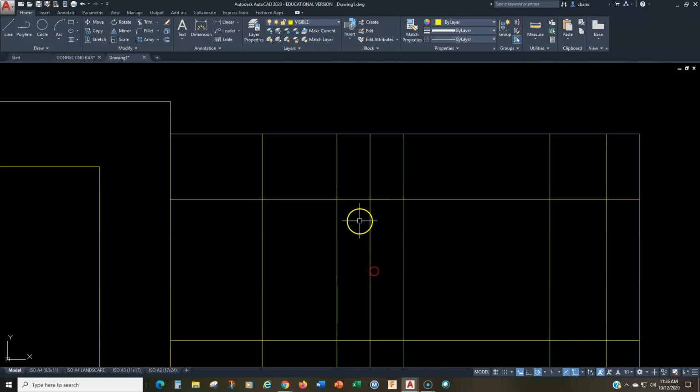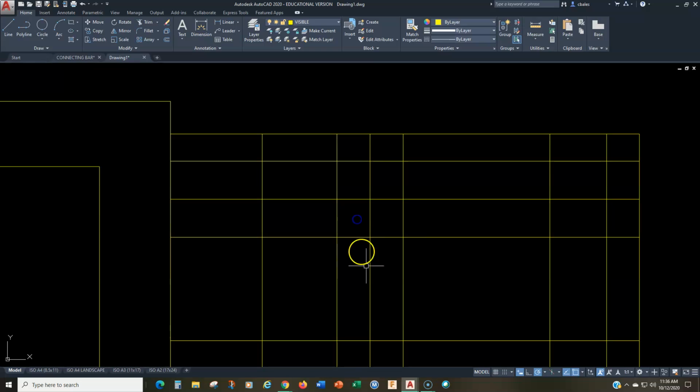We know that this is the center of the hole, and I'm not going to change it to center line because I'll just have to change it back. The hole has a diameter of 14, so that means the radius is 7, which means, remember, dimensions in this direction are not foreshortened, so I can offset 7, half of 14, in this direction. And that creates our ellipse.